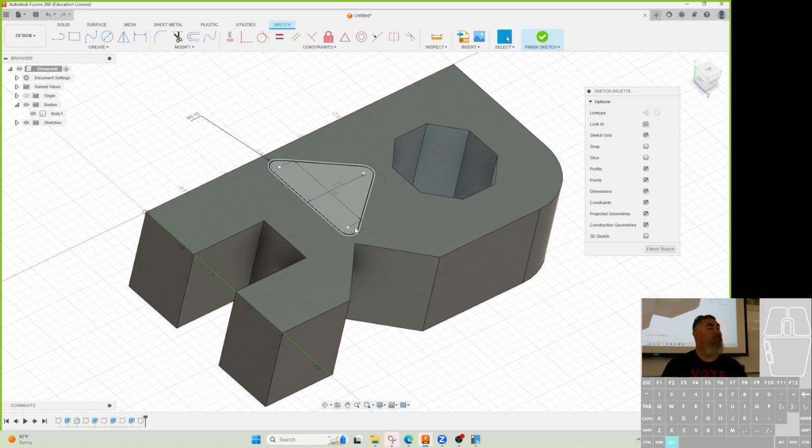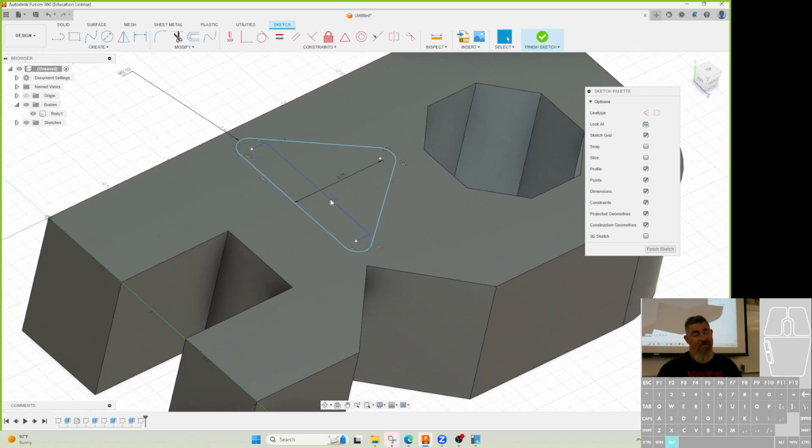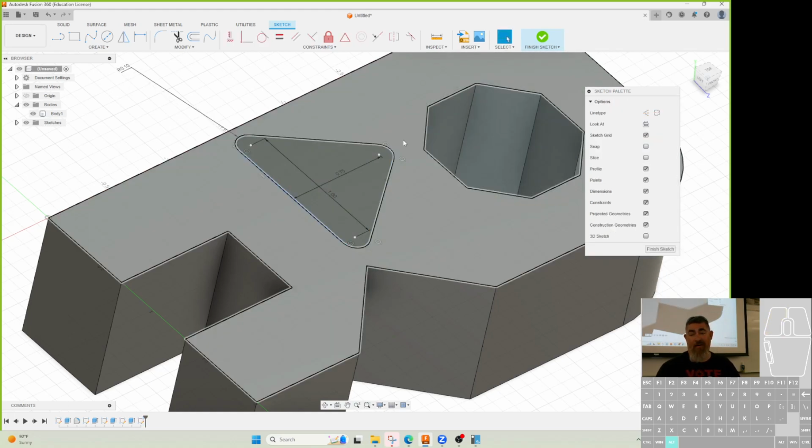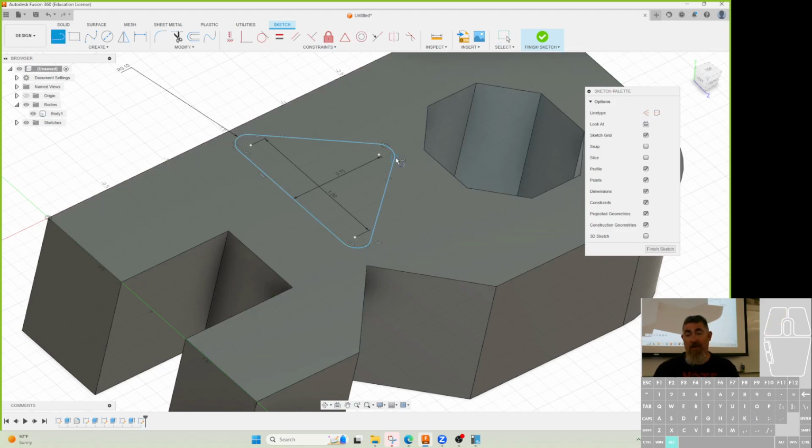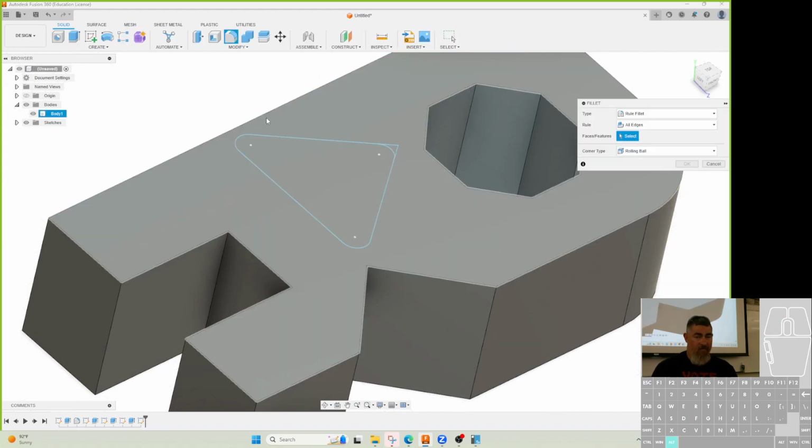Yeah. Just to review, the reason why on this particular one we're not using the sharp edge is because after we came through and used the fillet, we were not sure how much dip off, where it's going to be. Yeah, because here I'm telling you, I want the centers to be 1 inch apart, and then I want the center to be 3/4 of an inch up from that edge. So that's the other cool thing here, is we can kind of figure it out. So if I actually did want to do that, oops,